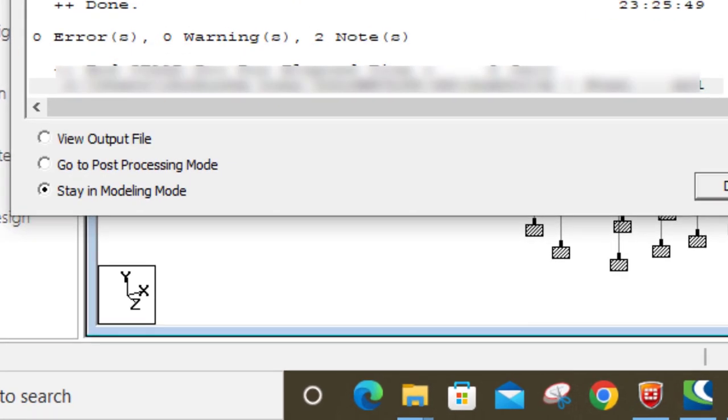Please. Okay, you see our analysis has gone through and is successful. We have 0 error, 0 warning. That's very wonderful. Last class, I think we had about 3 errors, and all of them centered on the type of circular beam we use, which wasn't taking our load. To be on the safer side, we have also already learned that each time you have a circular beam or a curved beam involved in your structure, try to model it using normal beams to create the curve, not using the icon there on Staad.Pro. So just create it with normal beam so that you don't have issues.